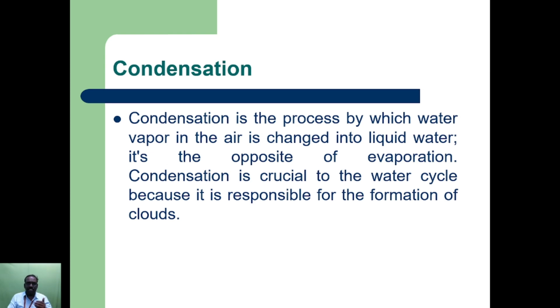Then we have the transient stage: Heisler charts, lumped systems, semi-infinite and infinite solids. The important number is the Biot number; for a Biot number less than 0.1, lumped system analysis applies. The same was discussed in these modes. What are the real applications? You can see them in turbines, nozzles and any engineering application. Then we covered the topics in terms of non-dimensional numbers, and condensation.